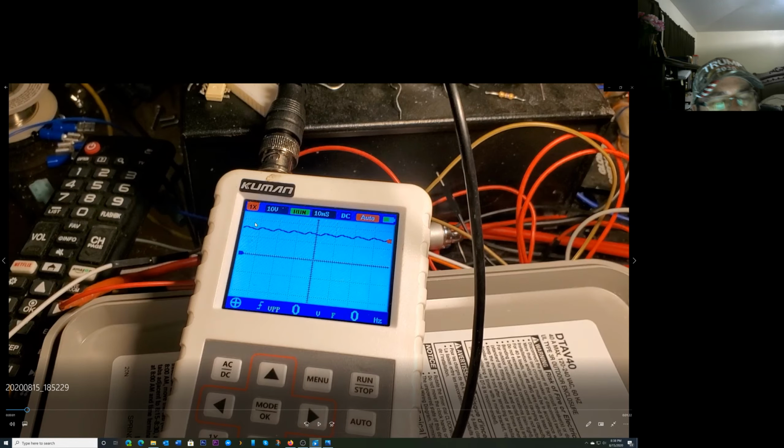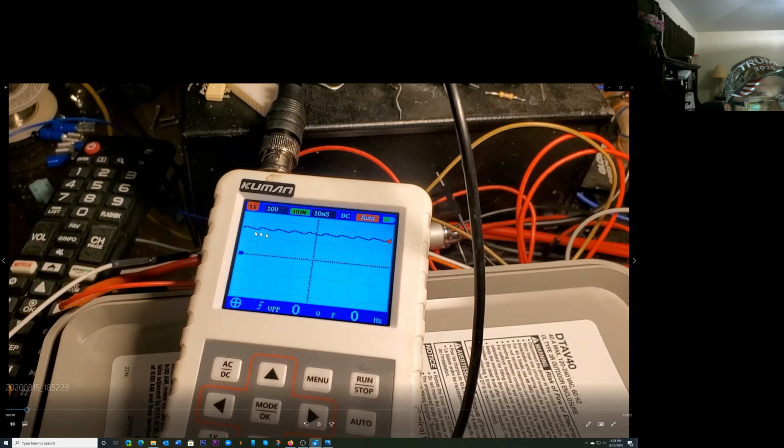And then there was something really cool I want to show you guys later. But basically, right here on its way up, this is the only time that there's current flow. Remember I was telling you I can't read the current with my amp probe properly? Well, it's because of this. Because once that AC sine wave is coming up and it hits this lowest point, it finally starts to pull current when the AC power is higher than the DC bus. And then on its charge right here, just from here to the peak, is the only time you're pulling current. Then it pulls no current all the way till here, pulls current, no current. So you're only pulling current this little spot.